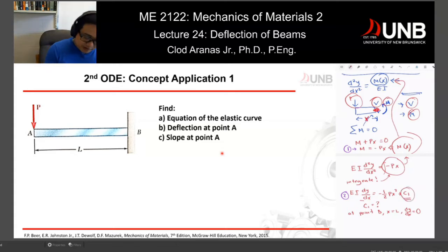Now, your constant of integration doesn't change from A to B. It's a constant, it doesn't change. So even though I'm going to apply any values associated with point B, it should not matter at all, so that I should be able to calculate what is C sub 1. Now, how can I calculate C sub 1? I have a value for my slope, which is this guy right here. I have a value for my x, and everything would fall into place. So I'm going to get the following after substituting these boundary conditions. I'm going to call it boundary condition number 1.